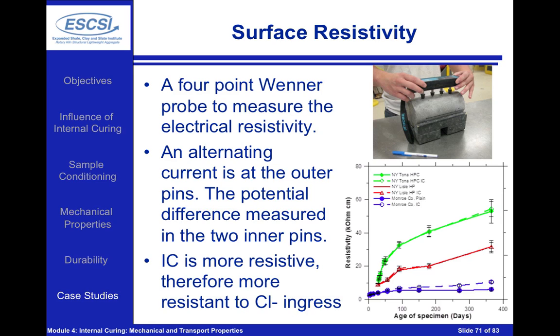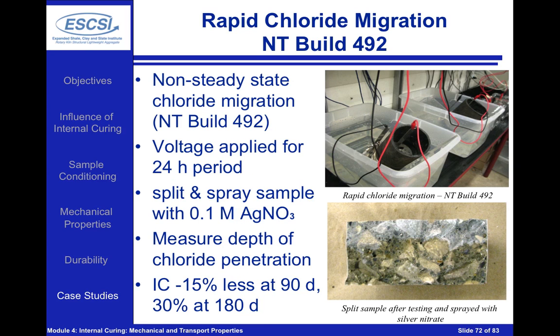Very similar response between the plain and the internally cured concrete. Slight reduction in the slightly more resistive internally cured concrete in Monroe County. Again, going with the fact that it would be more resistant to chloride ingress.